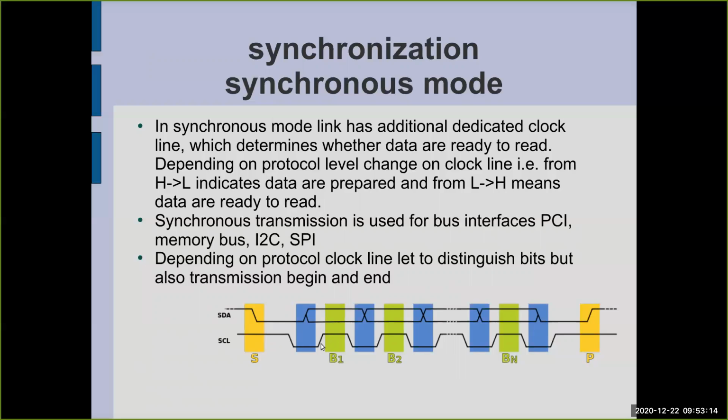So when the state is low, data are changed, or the state of the transmitter or data line may change, and when the clock changes its state, it triggers a read of the data line on the receiver side. So in this case, you can see that there is no problem with synchronization because every bit is indicated.